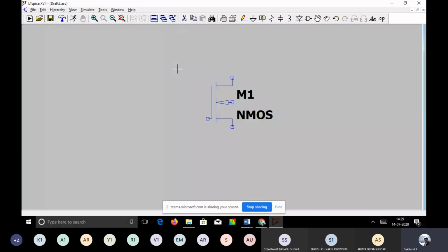Usually, these two files will be taken from different vendors. I may be working today with a MOSFET of one set of model parameters. Tomorrow I would like to work with other model files manufactured by some other company. So I can get the model file and the symbol file from them, put them in my own library, and then use them. That's all. So first, construct a circuit; second, make sure the model files are attached; third, do the analysis.